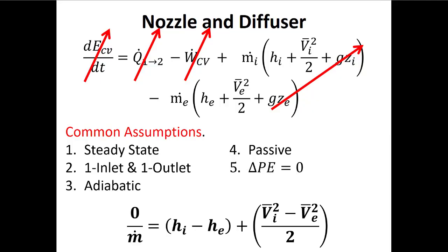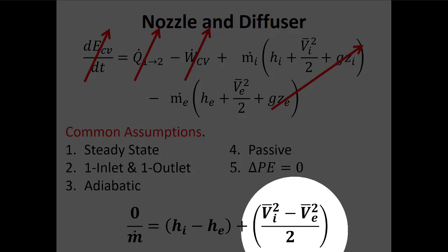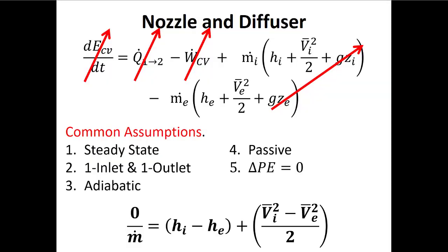Now, if I'm doing this, right, my spidey sense starts tingling because I got this kinetic energy term. I know that the units here are going to be messed up, right? And this is written as if it's in metric. If this is in imperial, then I would have to add that gc in the denominator as well.